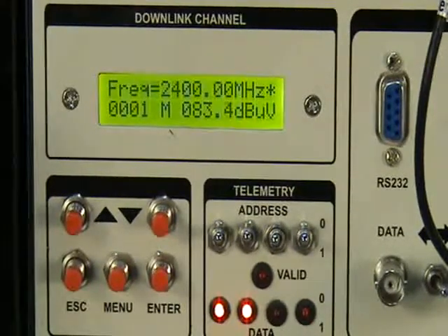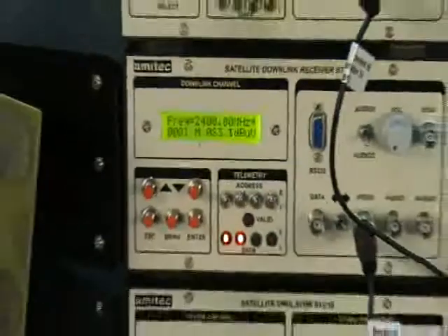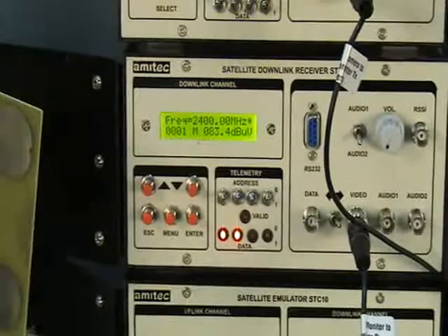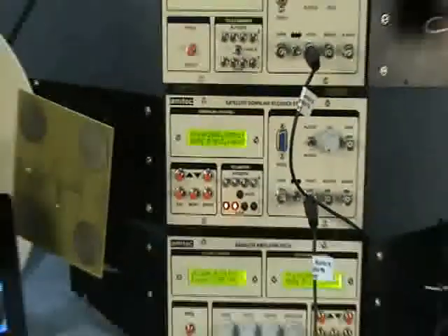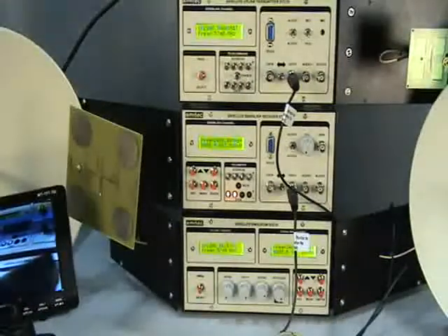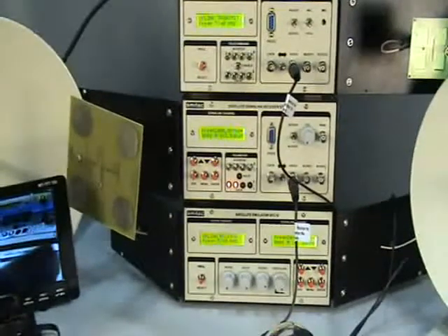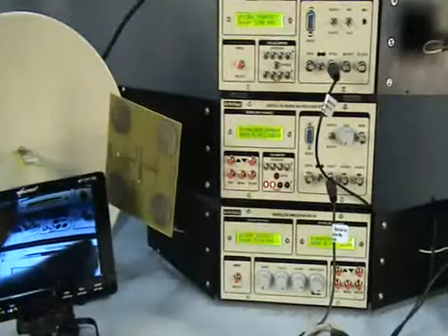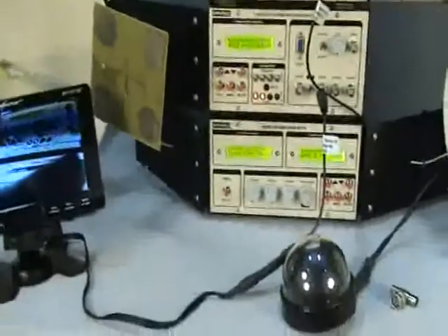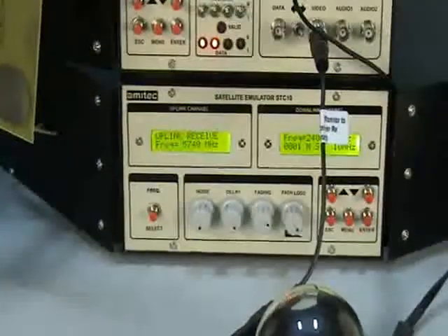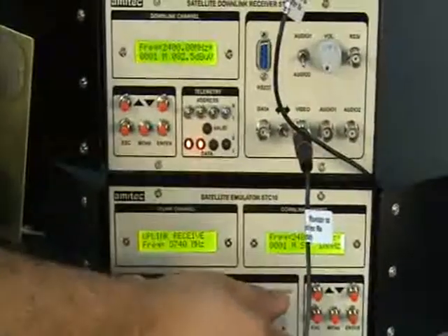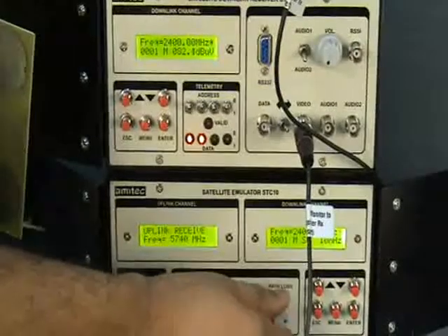So 83.5 minus 17 is the carrier to noise ratio of the receiver with a carrier level transmitted from the satellite. Now this carrier to noise ratio can be varied by using this path loss or attenuator. Now if I change the path loss,